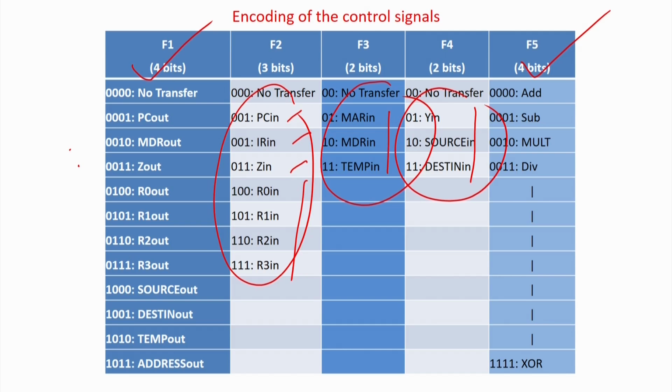That means they have found out that loading the updated value to PC and loading the IR generally does not happen in one cycle. So they have put it in one, and they have also thought that in the same cycle, when you are updating the PC, or an instruction is loaded into the instruction register, R0, R1, R2 and R3 do not read at the same cycle, because when a PC is updated, generally the temporary registers do not read the values.